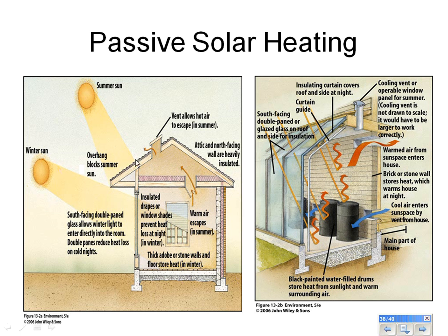So if you remember looking at this picture here, this would be a house in the northern hemisphere. And we said that for the summer sun, we'd want a longer overhang here. Even though it's called passive solar heating, it heats up the inside of a house without using pumps or a series of devices. It's also going to help keep it cool in the summertime. So here we have our summer sun that's very high in the sky. The solar radiation is being blocked out by this extra long overhang.